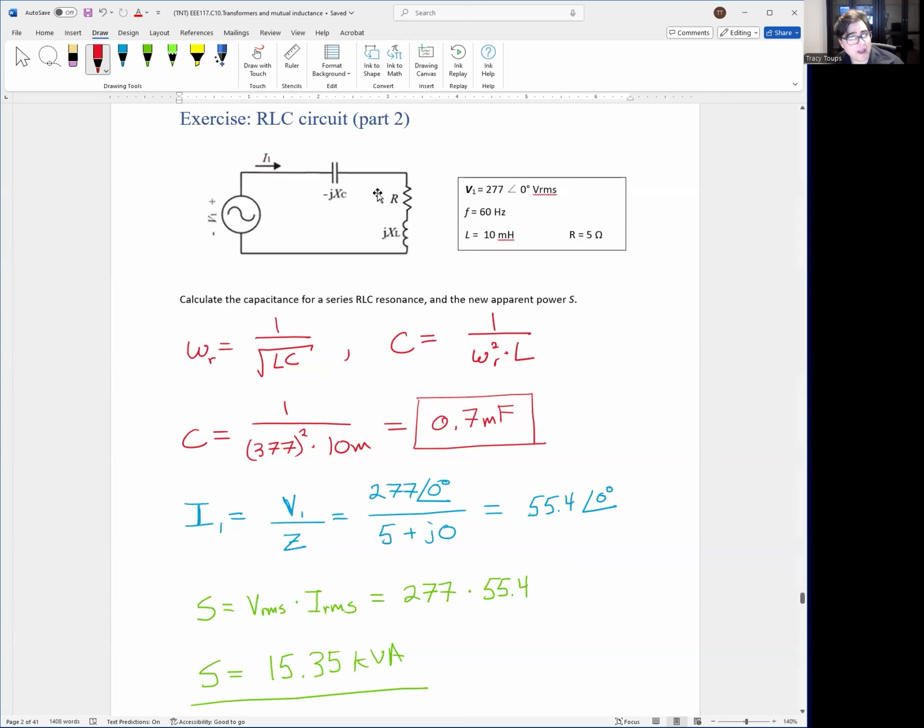But we could put a capacitor nearby in series with it, and that will help alleviate the energy draw of the magnetic field, because the capacitor will have the extra energy in its electric field to dump into the magnetic field of the motor, so they kind of help each other out and lighten the burden on the source itself.